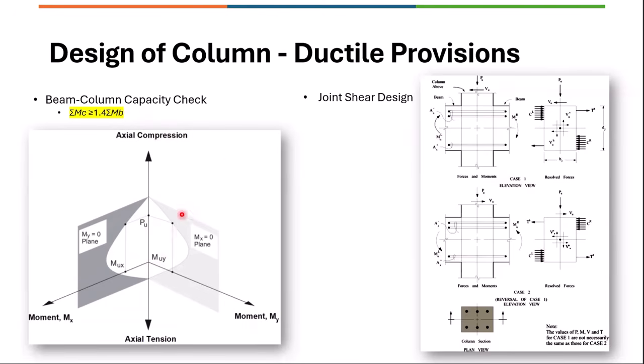In that, it works out the uniaxial bending to work out the capacity for the demand axial force, and that will be used as a capacity. And the enhancement is done to the demand moment, and that will be shared half above and half below columns.